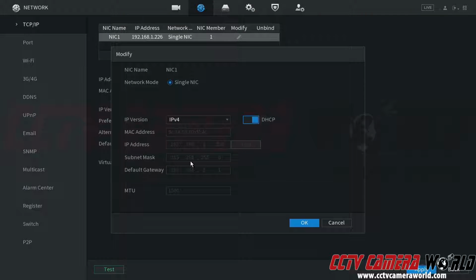If you see zeros here, that means your recorder either is just not properly connected to a router, or you don't have a router, or your network cable is bad. So if you're seeing zeros, you have a hardwired network connectivity issue going on. Or you may need to reboot your recorder for it to get an IP address by asking the router to provide a new IP address.